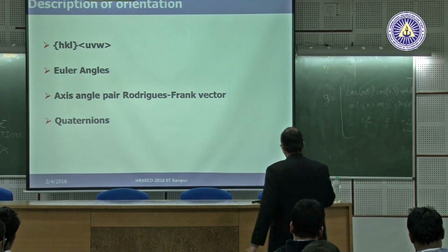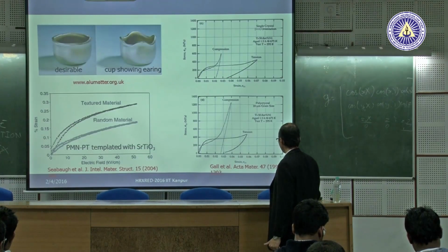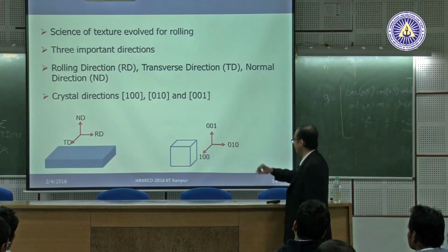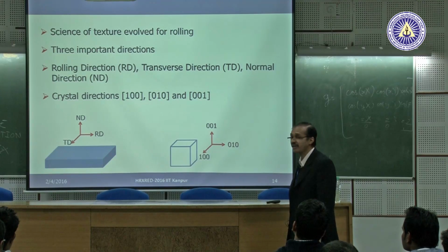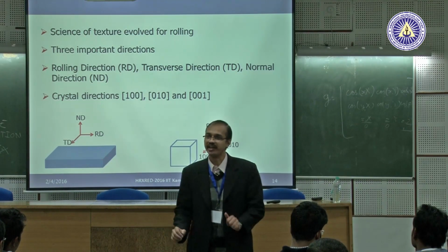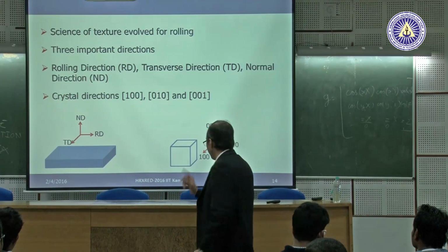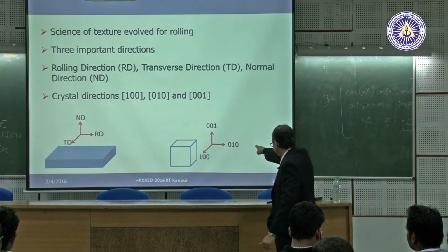So let me go back and tell you, let us look at this image. Which plane is lying in the ND plane? Yeah, 0, 0, 1, because though I am talking about a plane, I am essentially looking at a direction, since I have done orthonormalization. So you can always say 0, 0, 1. But the way I have written it, I write a plane.